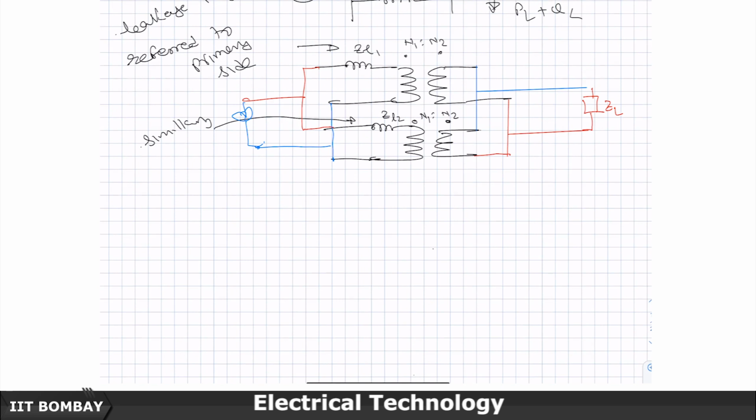See, this voltage is the same because it is across the loads and they are in parallel. Therefore these two voltages are also the same, and on this side the primary voltages are also the same, and the voltage drop happens basically in the leakage reactances shown here.